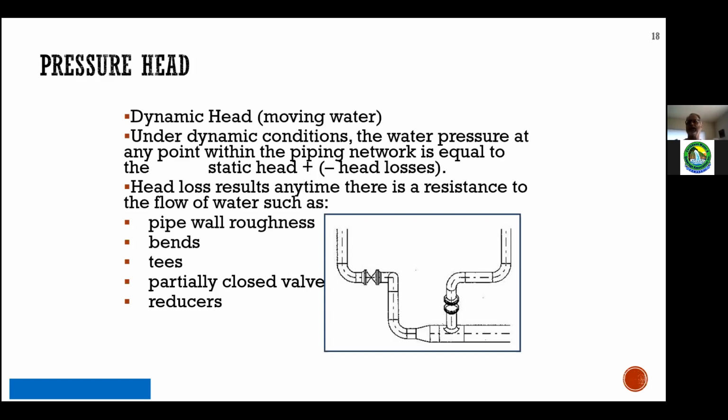And that's strictly head loss, right? The elevation hasn't changed, but head loss has overcome the static head in the system, which is why engineers then design different diameters of pipe based on how long the service is going to be and how much water the customer needs. But just as an example, when I was working in North Van, we had lots of elevation changes,